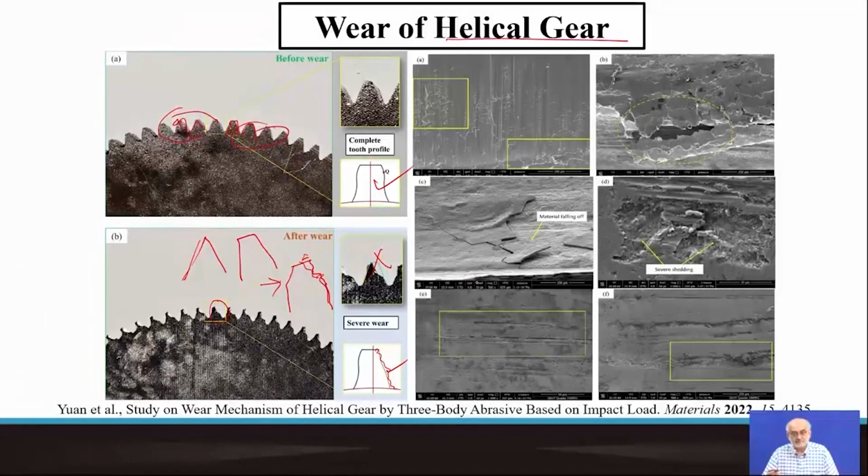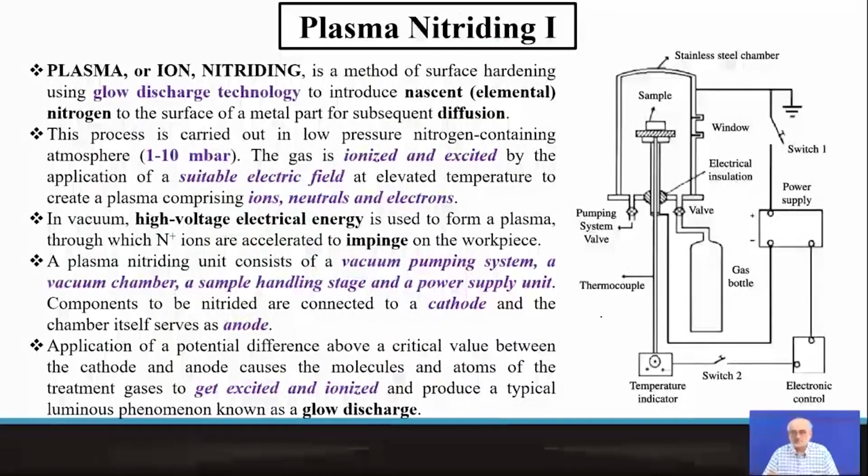Of course, liquid bath nitriding has its own dangers which need to be kept in mind, but gas nitriding is a fairly efficient and well-practiced operation through which one can improve the wear resistance of steel, iron bearing, or titanium, aluminium, or other alloys.